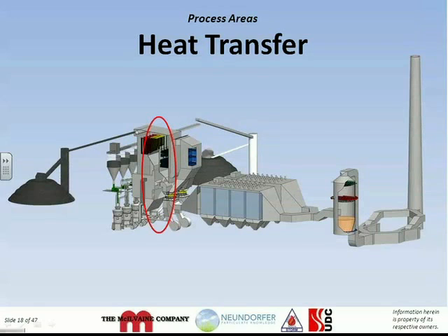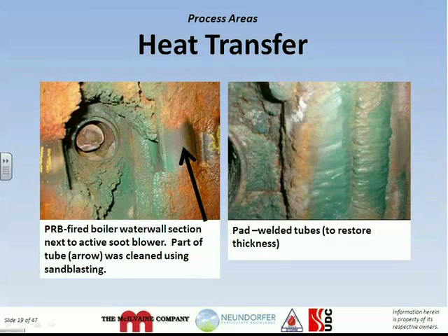the pressure parts. I can illustrate one example that exemplifies this fresh understanding of the entire process. Slag and the removal of slag from the heating surfaces, thinning, ranks near the top of preventable tube leaks worldwide. We provide access, sandblast cleaning. We do extensive thickness readings utilizing ultrasonic instruments, then process massive amounts of data in the quest of eliminating boiler tube leaks. This is followed by tube replacement or repair to restore the original minimum wall thickness, and adjustment and repair of the soot-blowing devices themselves.